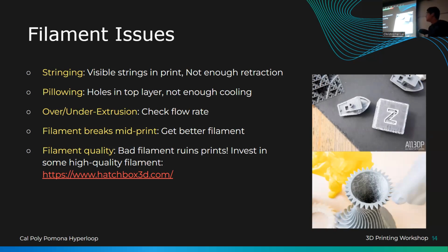That's why people do direct drive systems, where direct drive just means that the motor is sitting on the tool head, basically just pulling it out. The cool thing about direct drive is you don't have to pull it out nearly as far, and it's much quicker, right? The downside though is that you're adding more weight to the tool head, so you can't necessarily throw the thing around as much, right?